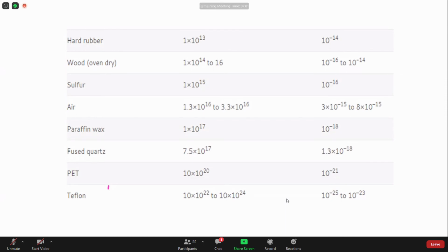right? The term resistivity is subject to how much voltage is applied. So if it was 24 volts and nobody got shocked, don't apply that same logic to 240 because that's a higher voltage. As the voltage gets higher, your insulator becomes a lesser insulator, right? So the rubber on your tools will have a range of voltage you can use it for. As the voltage gets higher, you can no longer use it.